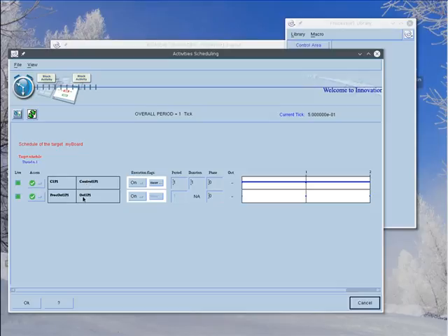Then, the hardware pin toggles its state. So, the two activities are on the same thread, the thread number 1, that has period 1. Consequently, the algorithm which blinks the LED is executed every tick time. Changing the tick time or the thread period, you can vary the blinking period as desired.